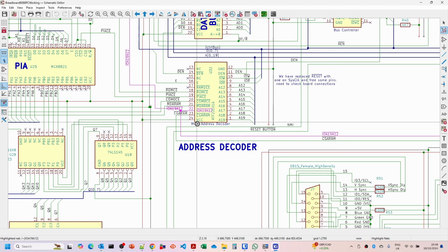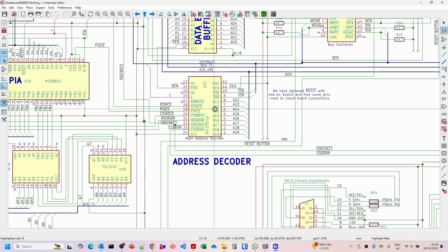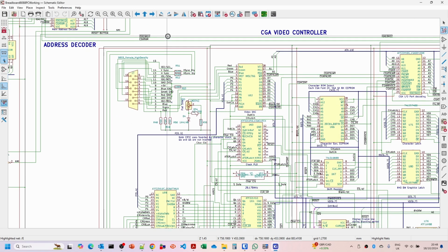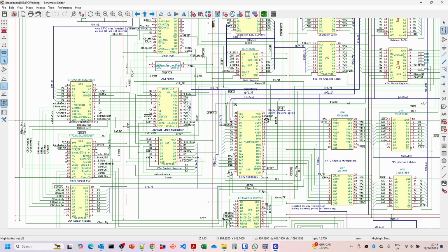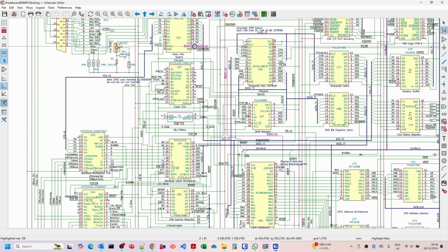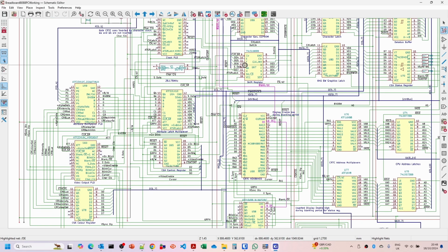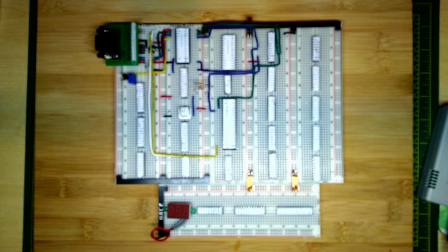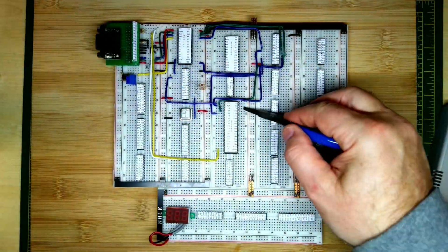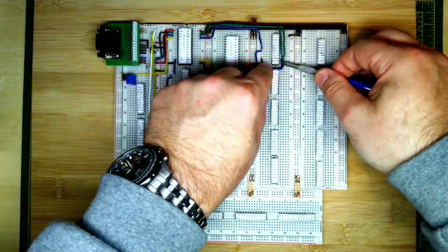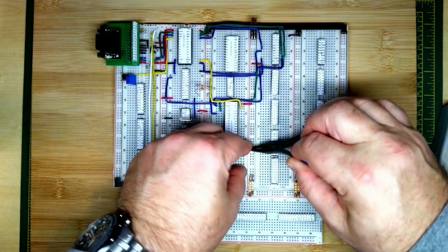So there's a couple of lines coming in from that main decoder: CGA RAM, the IO address 19 to address 12, and also the E signal. Those three things we're going to need to bring in from here, and we're also going to need to update that PLD at some point in time as well. Then the display enable output needs to go into the blank input on there as well. And reset, we can just tie that up to 5 volts for the moment until we wire in the main reset. So wiring in the IO write to read write, then this is the character clock, the blanking input to the video DAC, put in the power rails and then tie reset to 5 volts.